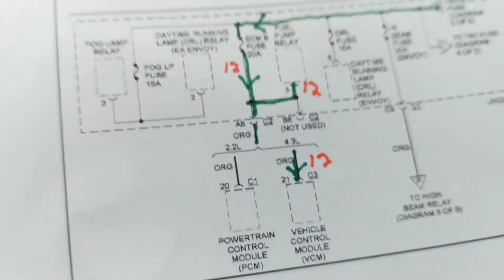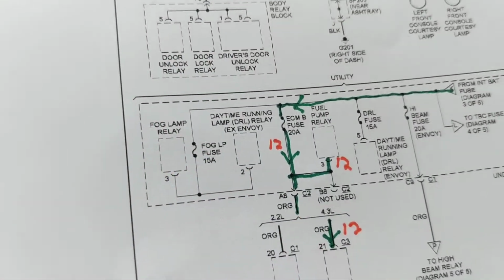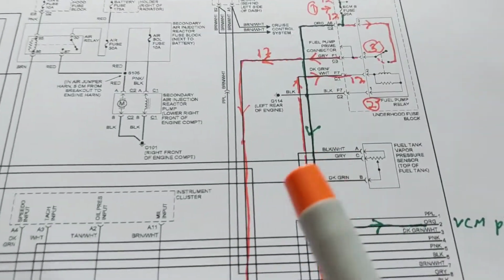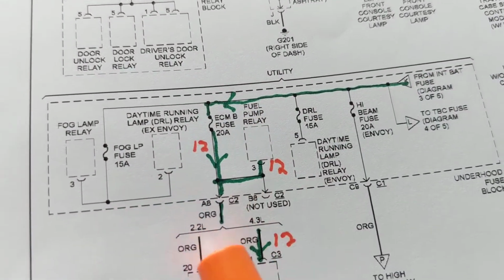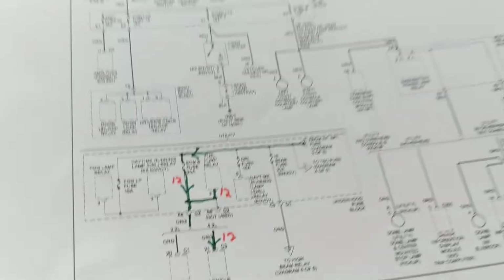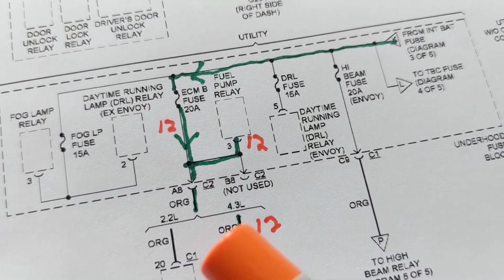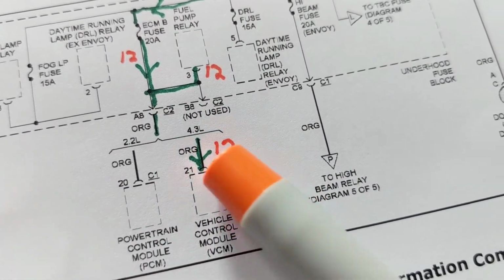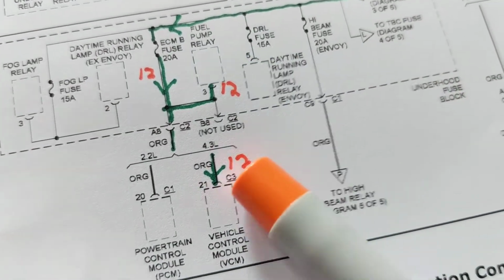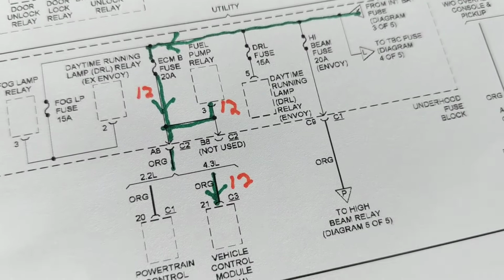It is right here. So this is much easier and simplified for the beginner to look at than going through this. That's why I recommend first find this, see where this is very easily. If this fuse is blown, what do I lose? I lose the relay and I lose the computer. No computer, no relay. This controls this. I'm going to continue on for ignition.